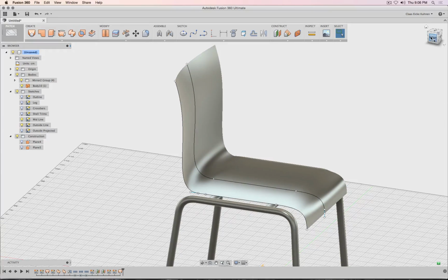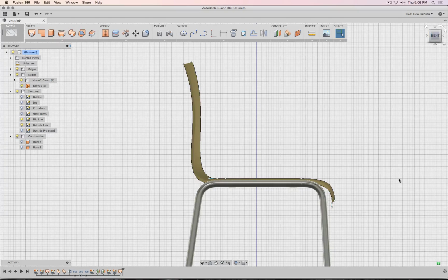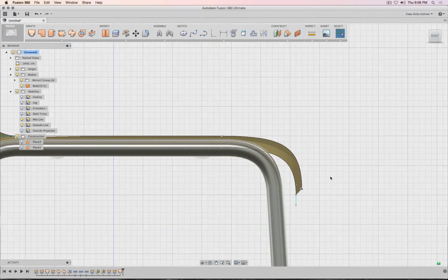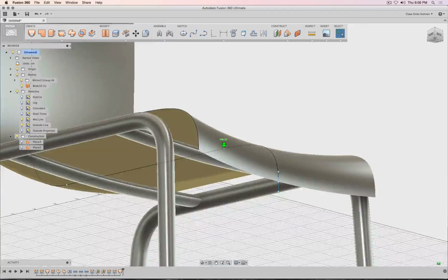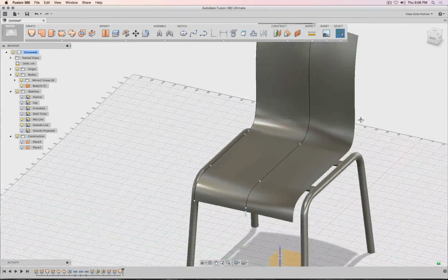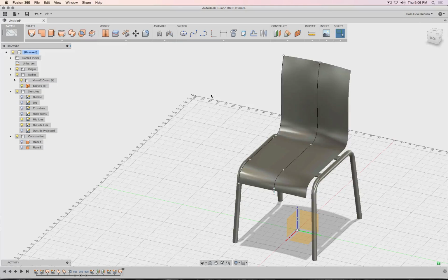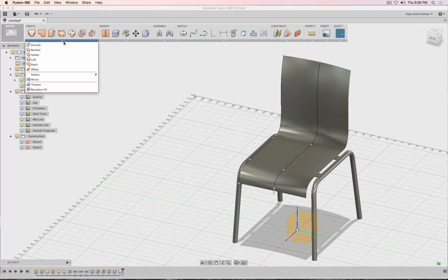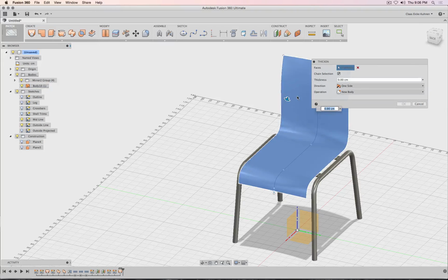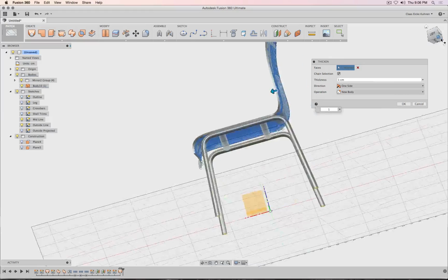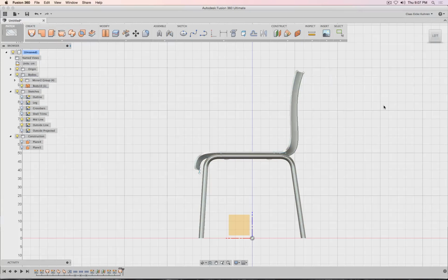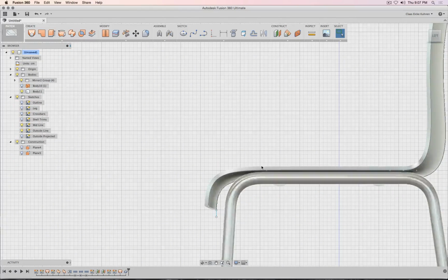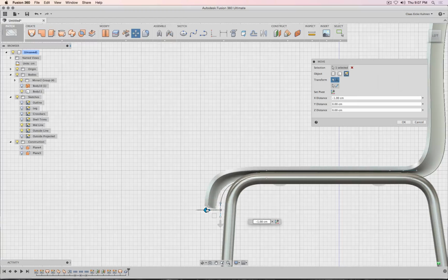So this is actually another quite nice way how you could create a shell and work with it. This point maybe now, let's move this one a snap forward there. Okay. And then to finish this one, basically would be the same. We could give this a thickness, maybe a centimeter. See, does it go into the right direction? Yes, it does. Okay. Now I feel like these points are way too far outside, so maybe select both points, move them inwards more.